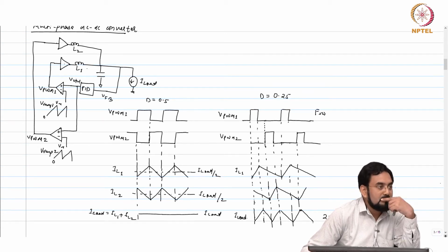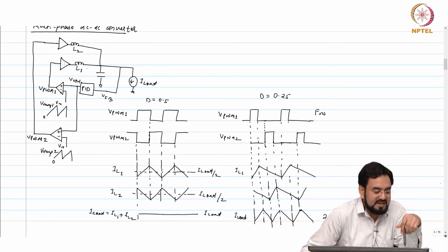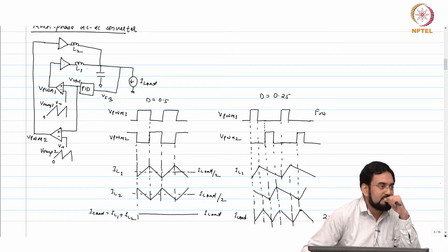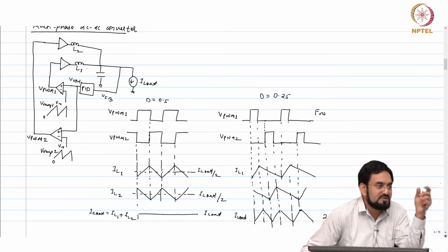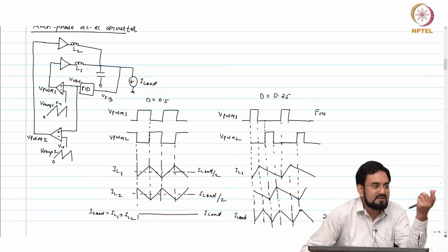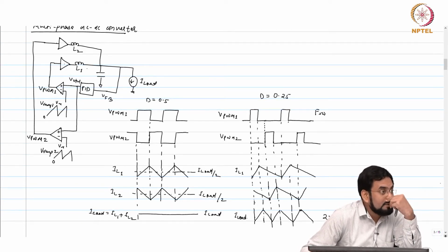So what you do, you equally split the power FET. Instead of sizing the same, let us say you require 100 milliohm for 1 amp, and now each will be catering only 500 milliamps, so split into half, so that your total area of power FET remains the same. But what about the inductor? I cannot reduce the size of the inductor.